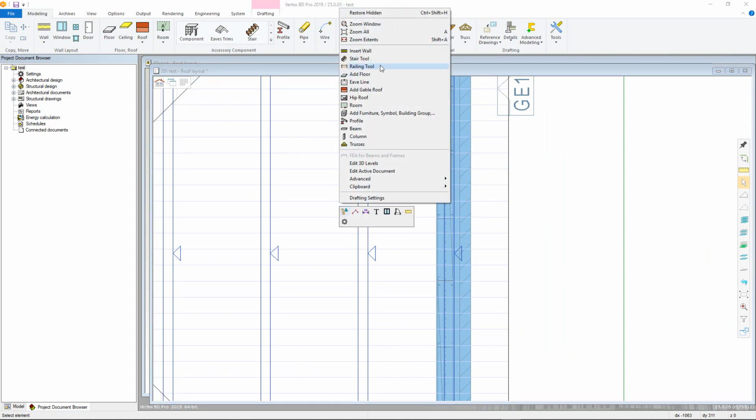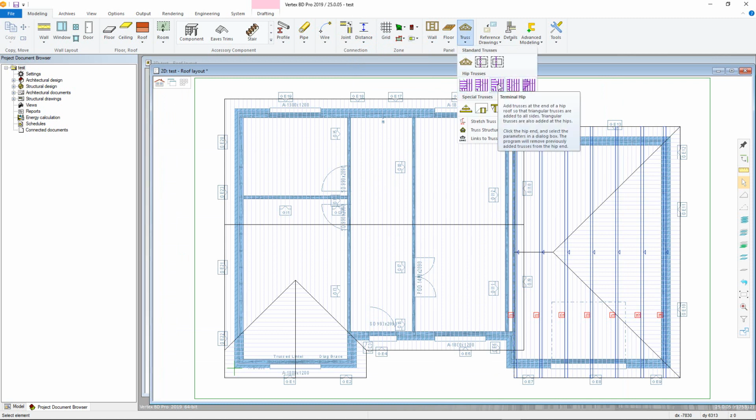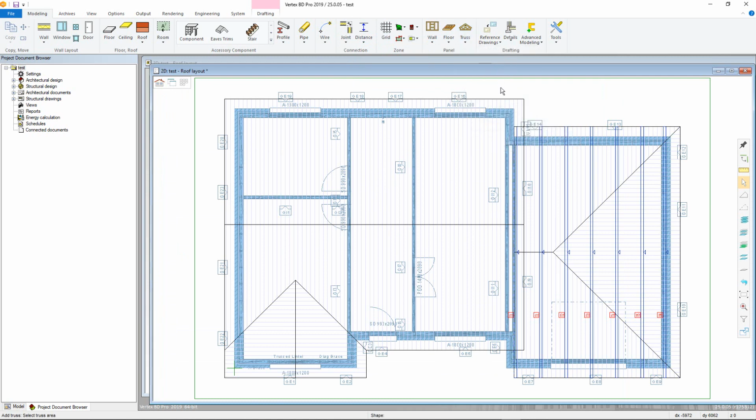However, there are more advanced functions for altering the truss layout for different roof types, such as this one. Go back to the Trusses menu, and in the hip truss section, you can choose from 5 different hip sets. For this example, I will use the terminal hip end option. Then I select my truss area, and finally the hip eave.